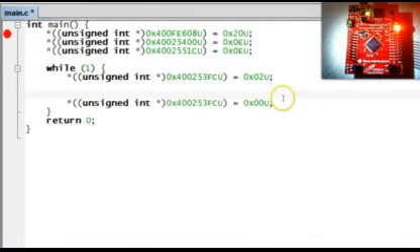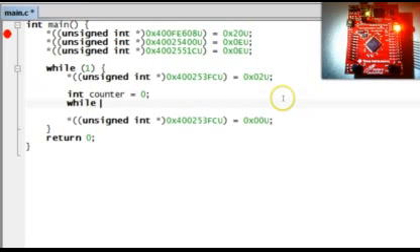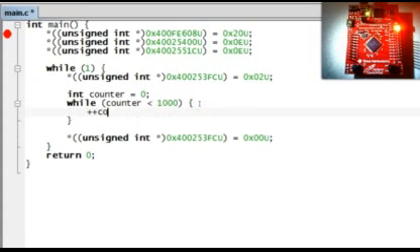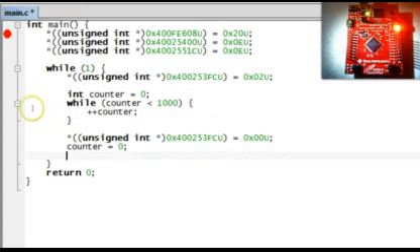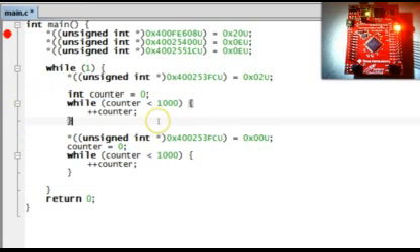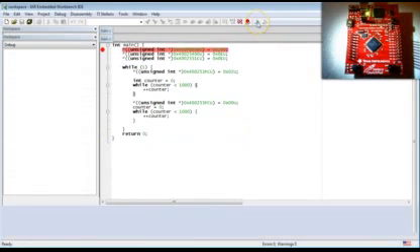For this, you can use the counting while loop that you learned in lesson 2. A loop like this wastes a lot of CPU cycles, but the delay can be controlled by setting the upper limit in the condition of the while. Note that you need a delay both after turning the LED on and after turning it off again. Alright, so let's give it a try.